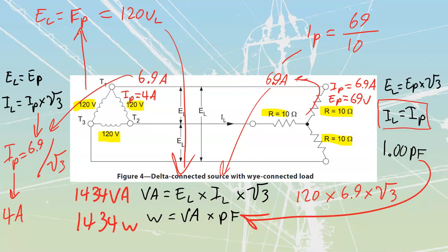All of the calculations out of Learning Task 4 are based around balanced systems. By balanced system, they mean that all of my load resistances are equivalent, so I have an equal amount of current inside each line. As soon as we have unbalanced loads, we have to do different calculations, individual, one at a time, until we can figure out what each individual amount of power is, and then add them all up. Thankfully, these are the easy calculations that we're still covering. So we've done the simple ones. We will get to the more complicated ones a little later on.